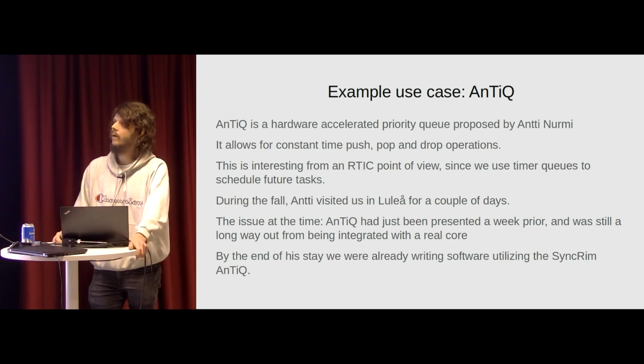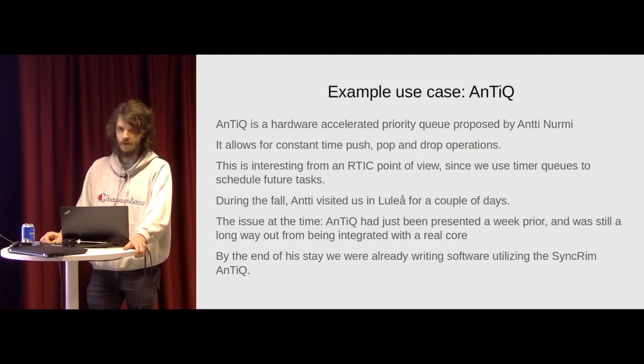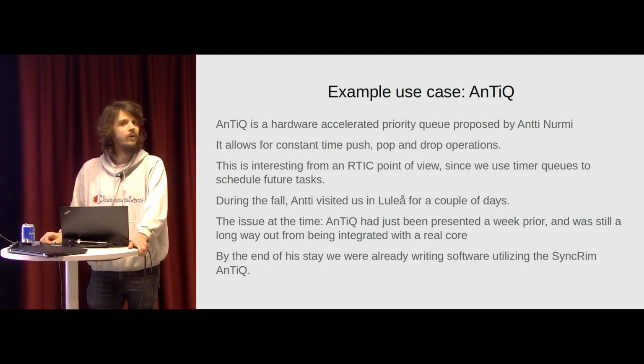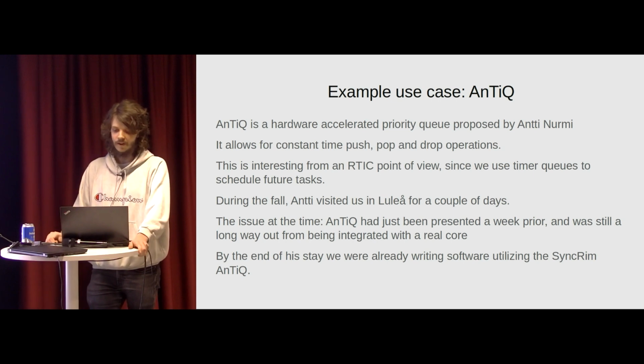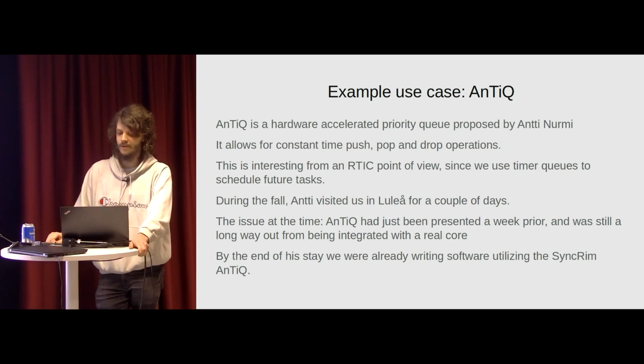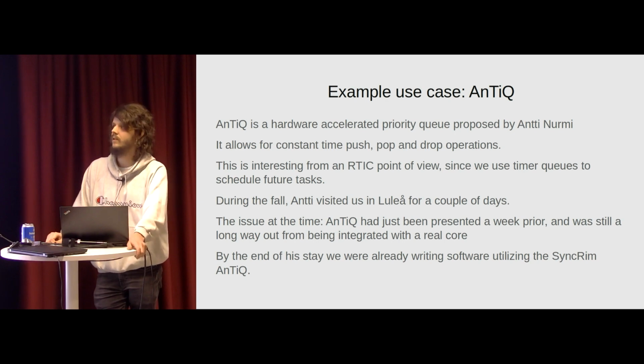Right. Another example is Antic, which is a hardware-accelerated priority queue proposed by Antti, who's here somewhere, I think. Yep, over there. And it allows for constant time push, pop, and drop operations, which is interesting for us RTIC folks, because we use timer queues to schedule future tasks.